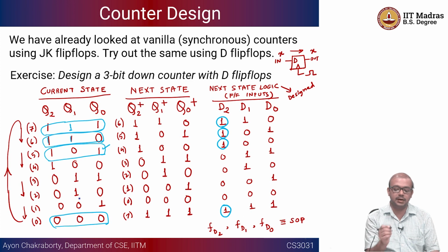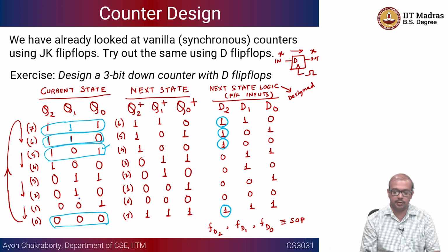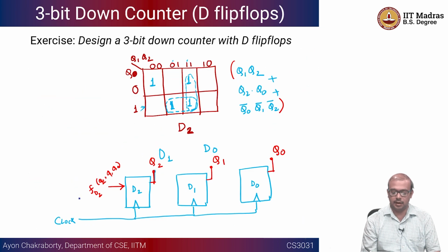We have specified it to work like this, that it has to follow this cycle from 7, 6, 5, 4, 3, 2, 1, 0 and back to 7. Okay, and we have understood the complete way how to design such circuits using a given kind of flip-flop, right? So I showed you one of those expressions. You can simplify the other expressions.